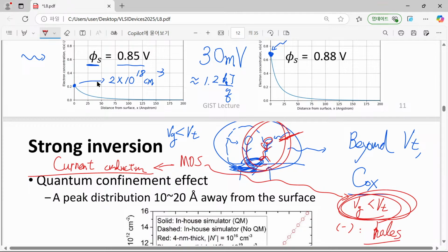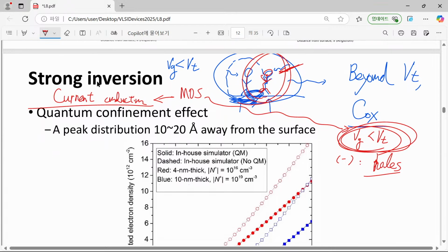Actually, depletion of holes. So at the surface of our MOS system, oxide and semiconductor, now when you have such a thing, we have no mobile carriers at all. Although we have negative charges, they do not correspond to negatively charged mobile carriers. There is no carrier at all.